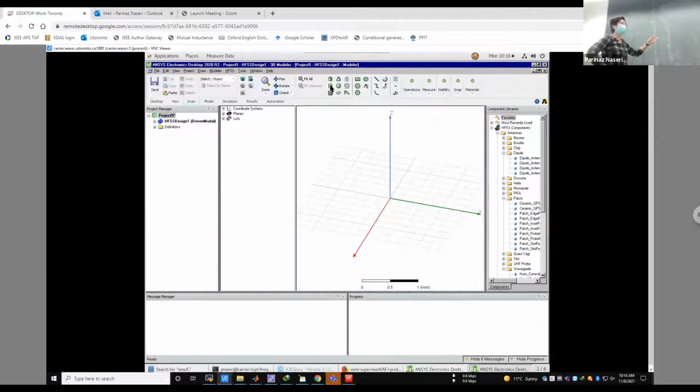And then if things are not going your way, you can adjust the lens, the different parameters to optimize it, and then apply the realistic cases, right? Okay, so what I'm going to do here, there are 2 ways to draw this. Either I can have a cylinder up here, a cylinder up here, right? Draw 2 cylinders. But another way for me to do it is just have one large cylinder and then define a gap cylinder here and subtract this from the main cylinder. So both ways is okay.